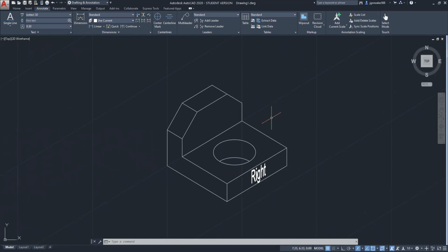Okay, so now let's try doing text on the left, right along this wall here, the left side. So switch to ISO plane left. So now my cursor is along this left side. Choose ISO text negative 30, the template we made.